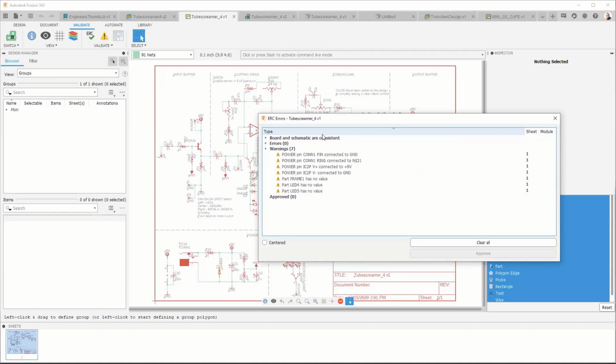Okay, got it. So the recommendation is, once you reference a board and reference a schematic, run ERC. It's the first thing you should do, just as a sanity check. You shouldn't get any surprises, but like many things, when we start something new, we have a little bit more concern and we're a little bit more unsure. This is a nice sanity check, letting you know that everything's okay.